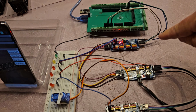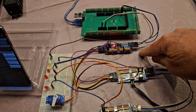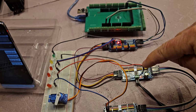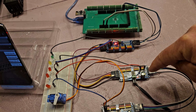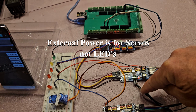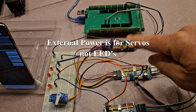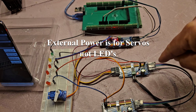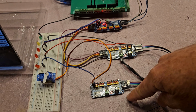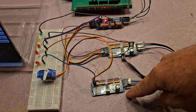Then I've got the 4 wires coming to the first PCA9685, address 0x40 as defined in DCC-EX. And then it daisy chains to the second one, 0x41, also predefined in DCC-EX. This is where my wall power is connected for the 5 volts that drives the LEDs and the servos. So I only need to connect in one place, and it doesn't matter which one, I've got it connected to the middle one. And then wires coming up to the third one. Now, this is one that I've added and addressed in the myhal.cpp file. Its address is actually 0x44, it's just one that I had.